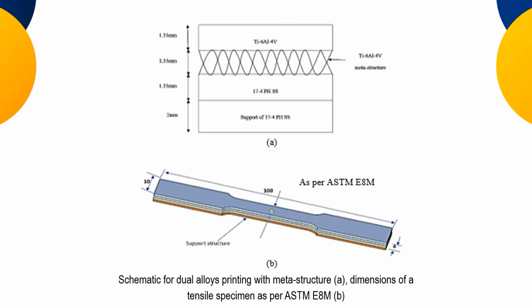the metallic part layer by layer, the one basic thing we understand is that once I have a building of the part, first there is an application of the support material. This support I can select. I can think of a solid support, a support like a pillar, or a support like a honeycomb, right? Normally, by default, the machine makes a support of around 2 mm. So up to this length there is a 2 mm support.